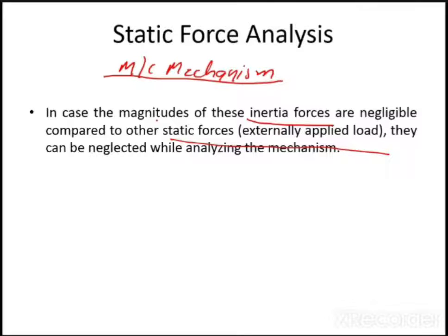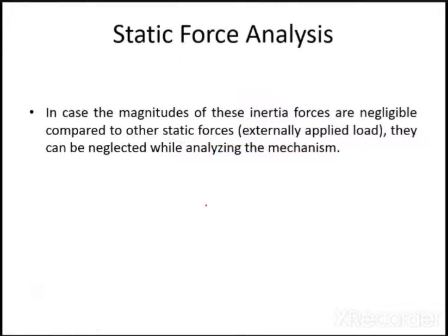Static forces are the forces which do not change in magnitude and direction. The forces which do not change their direction and magnitude are called static forces, and the forces which change their magnitude and direction are called dynamic forces, right? So if the static forces are very, very high in magnitude as compared to the inertia forces, then we neglect these inertia forces.